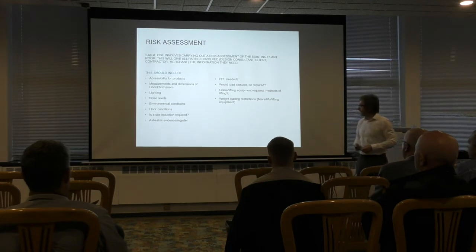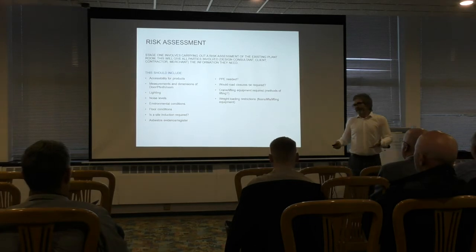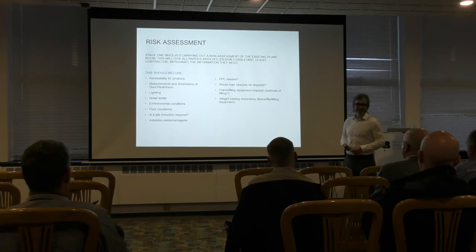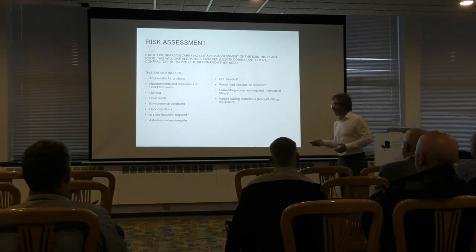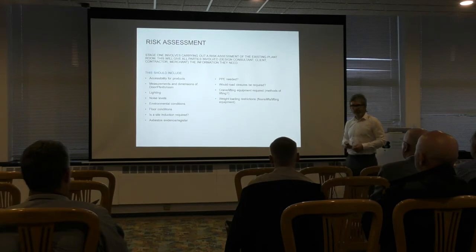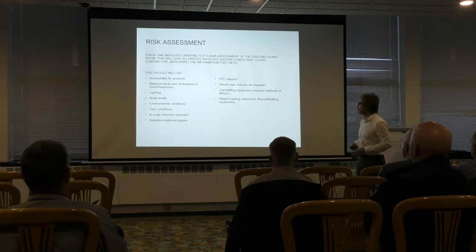Last point on that side there, the asbestos register. Again, probably the most important thing you want to be looking at. Older buildings riddled with asbestos, and the last thing you want is to forget to look at that, and then you get your contractor going to site, starting to rip the ceilings down and old flues out, and all of a sudden you've got asbestos dust everywhere. And I speak from experience recently. There's a project which I'm involved in down in London where I got told the other week that the project had been put back 2 weeks because they found asbestos on the site. Really, that should have been picked up on the initial survey.